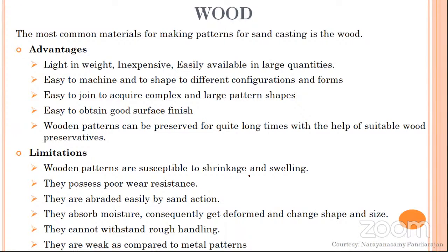As the wood absorbs the moisture content, in due course of time, you will lose its dimensional accuracy. Thereby, the wooden pattern becomes dimensionally unstable after a certain period of time.